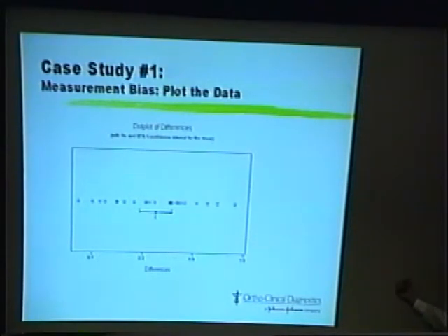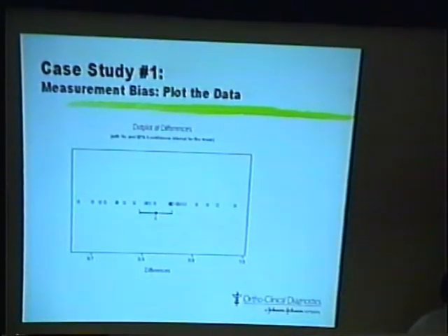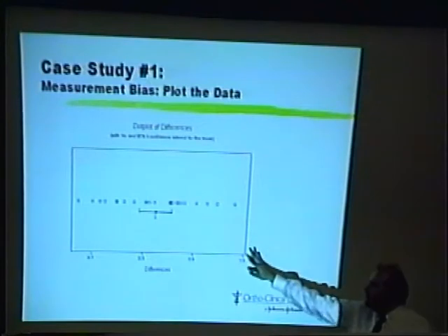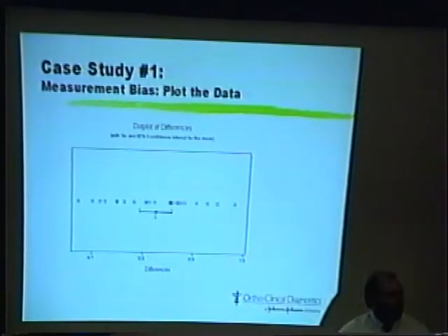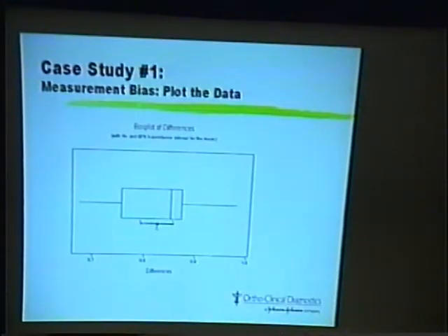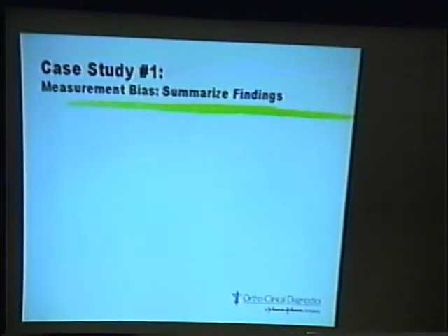Another option in doing a paired test is a dot plot. So I won't talk about the applicability of one or the other, but in any event, we've got a dot plot with a confidence interval for the mean as well. And those come automatically, as does the box plot. So choose your weapon, but the nice thing is that in many of the Minitab statistical techniques, they give some guidance in terms of what graphs or plots you might want to use. And I've found them to be very appropriate in all cases.